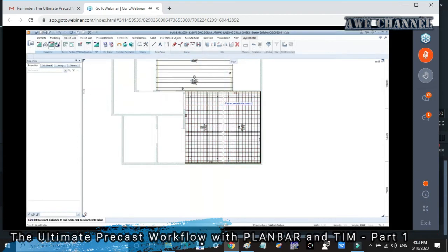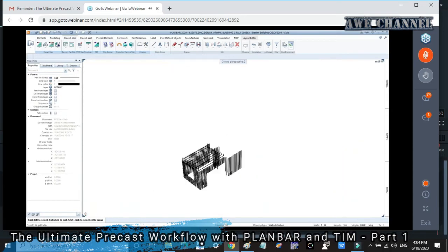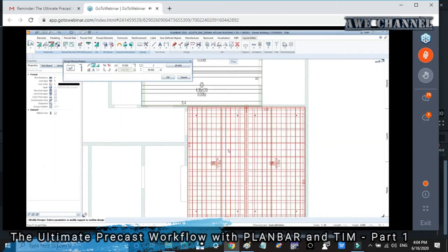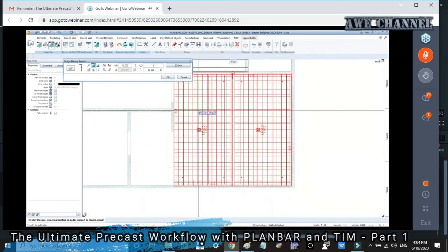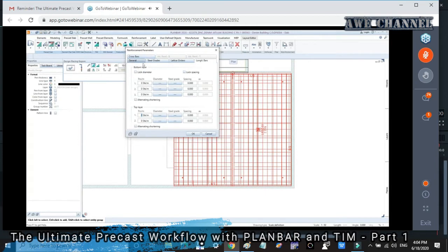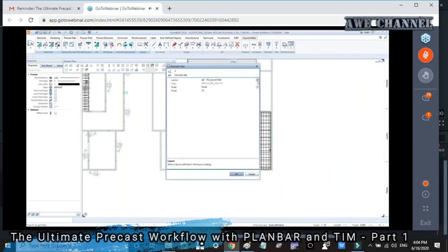Okay, so regarding slab element, I have more possibilities to show you right now. If you want to change steel gauge, you can do it here, and you can even add more reinforcement by using attached reinforcement. You can go to longitudinal bars and crossbar. And of course, for the shop drawing, you just click on it, and then you will get the shop drawing